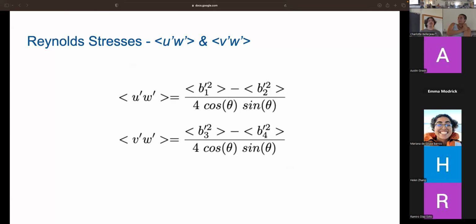No. You can. It just adds a huge thing. I can send you guys a paper on that if you want, but it takes this nice succinct thing and makes it this long thing, adding in the fifth beam. So again, that's just to reduce your uncertainty. Actually, interestingly enough, adding that fifth beam does not appear to help with your estimates of Reynolds stresses too much, from what I've seen in the papers that I read. So, interesting note. But yeah, that's that whole bit.